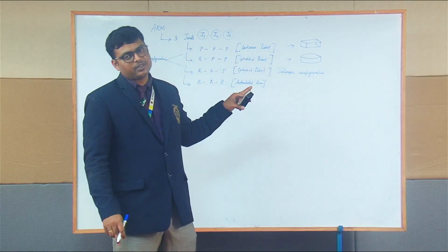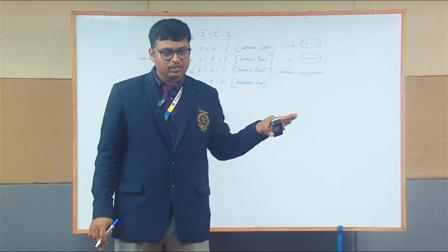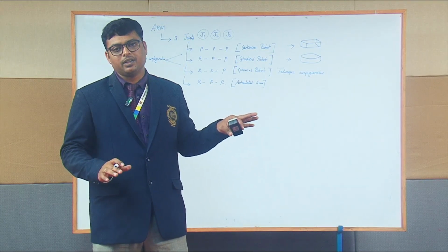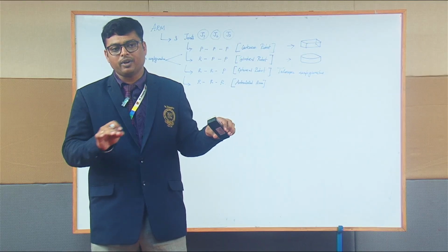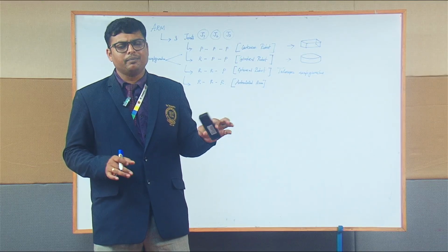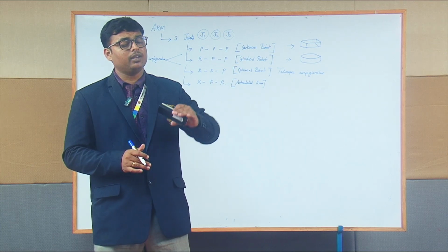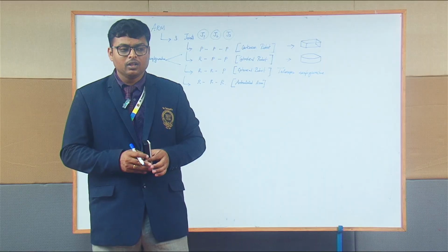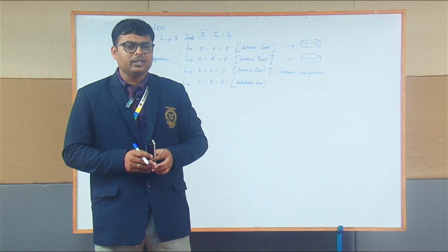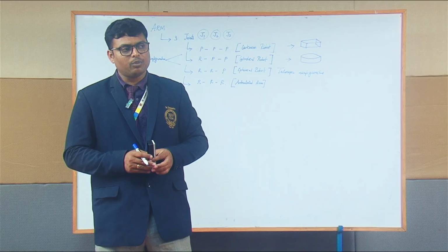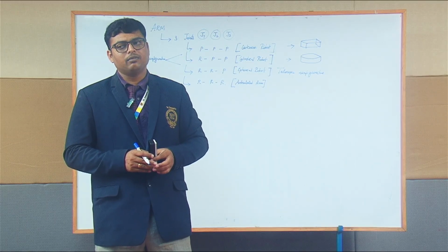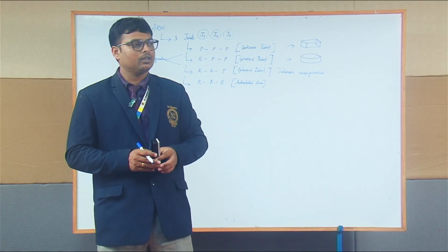has the maximum efficiency in covering the workspace. So just like your hand, you can wave around, you can reach the points, intermittent points. It has many lesser dead zones comparatively to the above 3 configurations. So the robot companies prefer articulated arm. Any robot type if you choose, it will have articulated arm configurations to be definite.